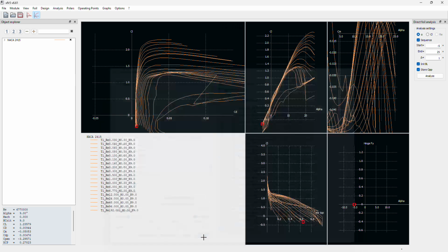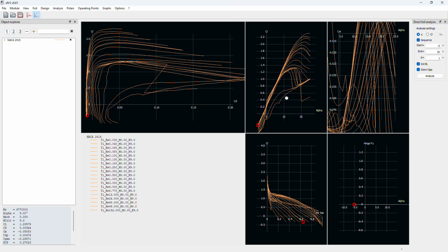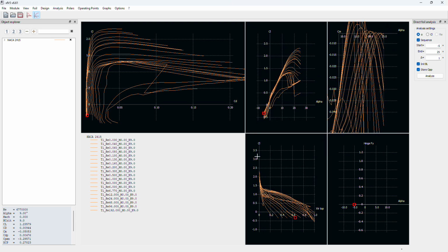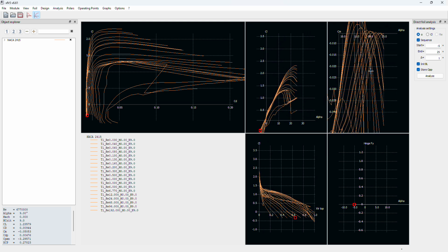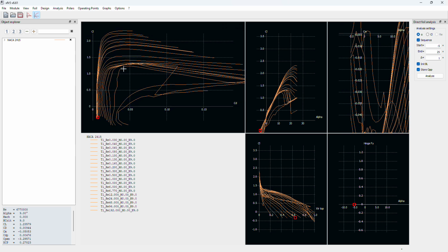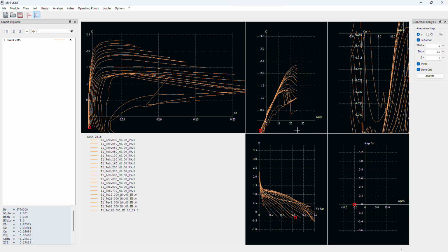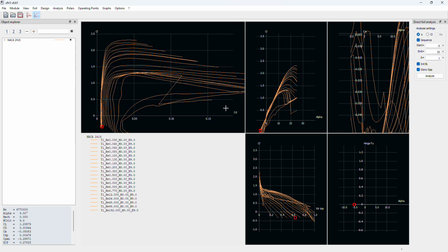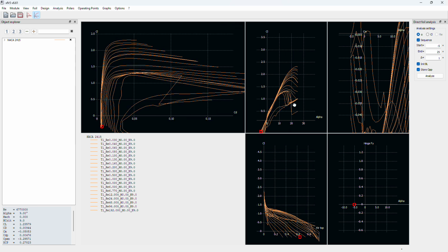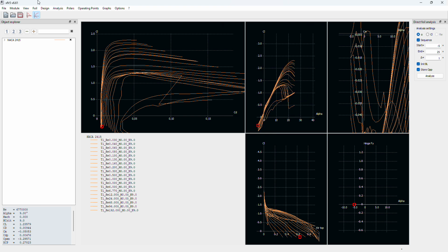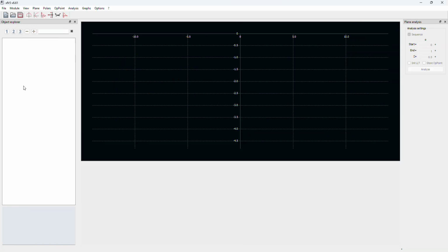So we complete the analysis. Now we have this. This is what it looked like before. There are a few different Reynolds numbers that seem to tweak out, but it hasn't affected my data in any way that I can determine. Everything looks solid for the wing. I couldn't get rid of these discontinuities, and I thought it wasn't wise to start chasing them. It's kind of impossible. So after this, I switched to wing and plane design, and then did the geometry.